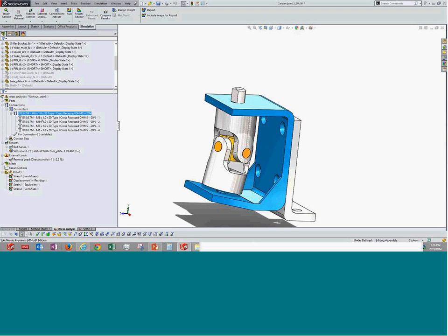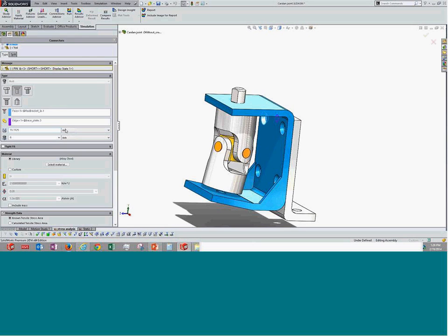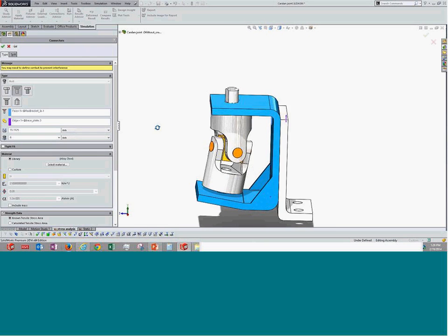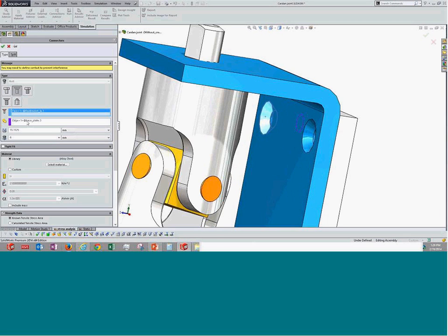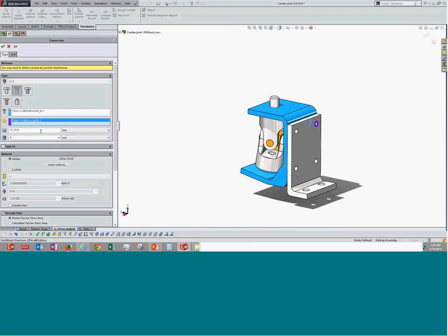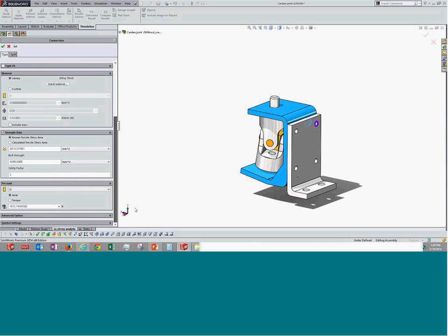You select as asked over here the conical face where it is going to be fixed. You need to set the appropriate kind of bolt, and the edge on the other end, the head diameter, length again, and axial. Axial would be the option that we are selecting and creating these four bolts here to connect these two parts.